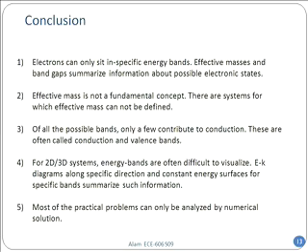Effective mass, I said, is not a fundamental concept, and there may be systems where the effective mass cannot be defined properly. Do you remember the graphene relationship? You should also convince yourself how to think about carrier transport in those cases, and how to think about the negative effective mass or zero effective mass in those cases. The third point was that only a few bands contribute: conduction and valence band, partially empty or partially full.